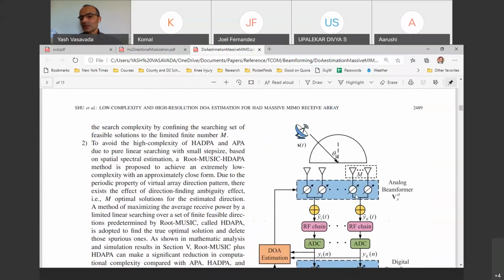One thing that they are allowed to do is they can put some analog phase shifter, which they are showing by this symbol, on each of these 100 antenna elements. But then they have to combine the output, possibly after phase shifting. Phase shifting is optional. If they want to do it, they can do it. Otherwise, the output will just get combined.